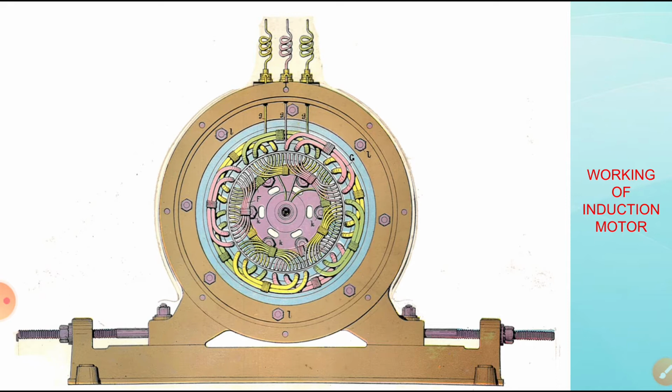It works on the principle of induction, where an electromotive force is induced into the rotor conductors when the rotating magnetic field of the stator cuts the stationary rotor conductors. We will elaborate this basic principle with the help of diagrams.